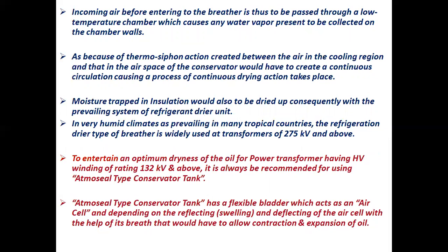Incoming air, before entering the breather, is passed through a low temperature chamber, which causes any water vapor present to be collected on the chamber walls. Because of the thermosiphon action created between the air in the cooling region and that in the airspace of the conservator, a continuous circulation is created, causing a process of continuous drying.